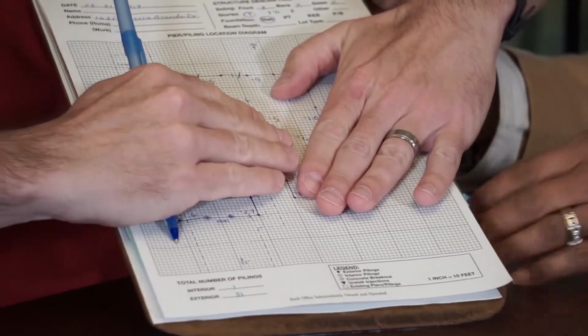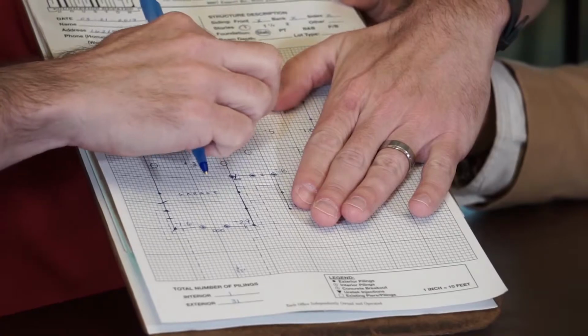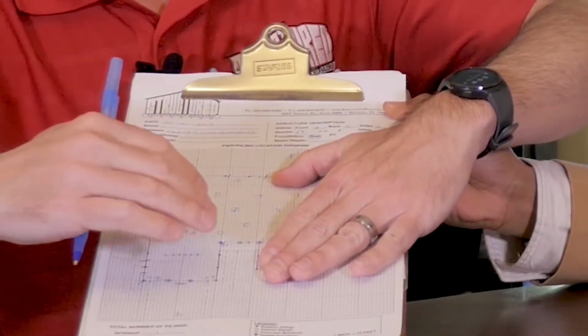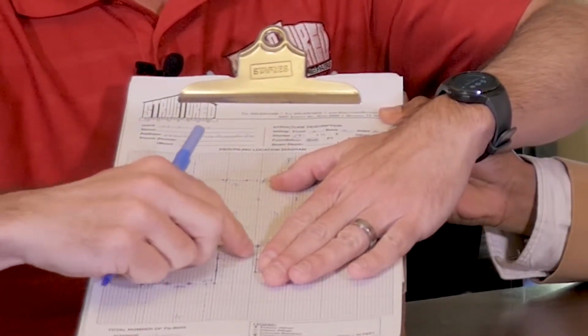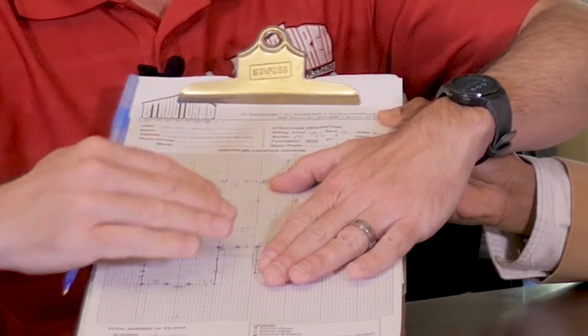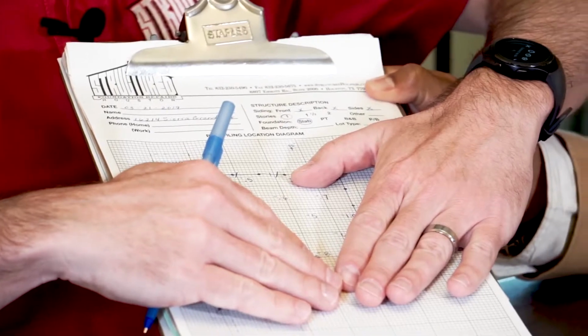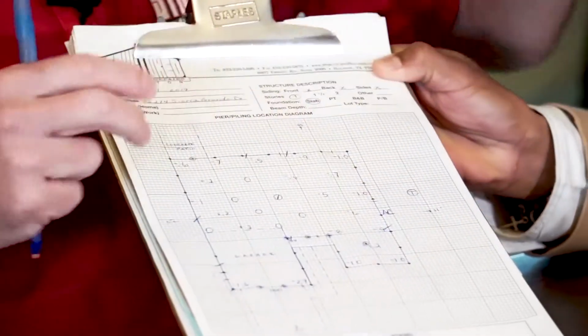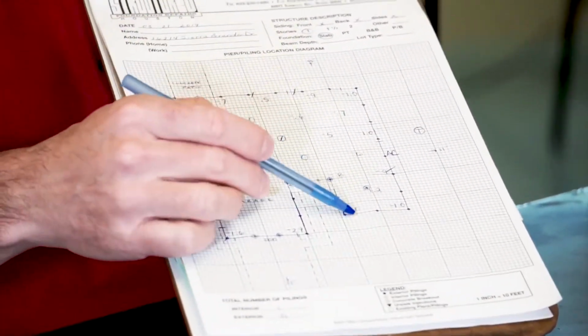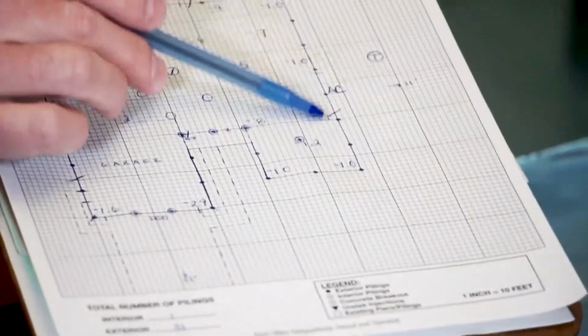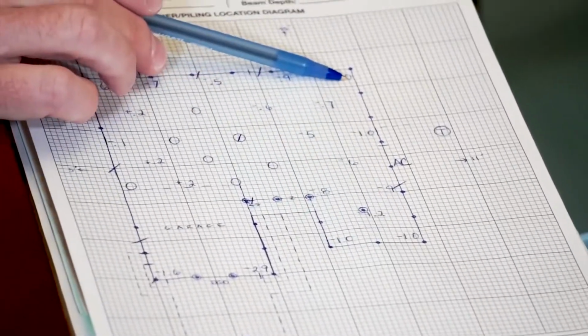So in terms of the house that we're looking at here, I'm gonna have a little bit of a hard time doing this, but if I cover these numbers up, and I cover these numbers up right here, and I look at these remaining elevations that you may be able to see well or not, they all measure mostly within about 1/2 inch, okay? That's really good. That's what I like to see on a house that typically doesn't have a problem. When I move my hands, then I can see where I'm down 1 inch, 1 inch, 1.2 inches, 0.9. I'm at 1 inch all the way up here.